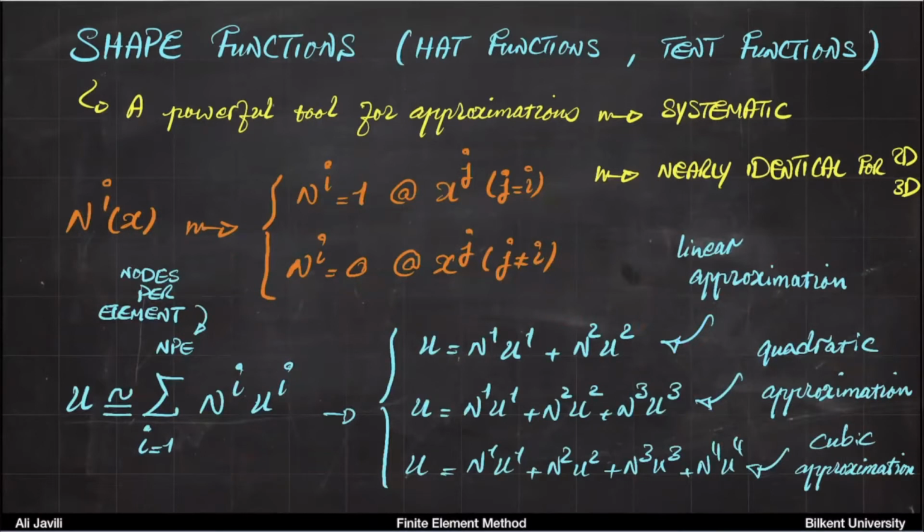And then based on that, you can write your displacements as a function of those hat functions. But also remember that these are displacements, and we mentioned that we use this thing that we call Bubnov-Galerkin and isoparametric concepts, meaning that we use the same approximation for u, for x, which is the coordinate itself, and for w, which are the test functions too.